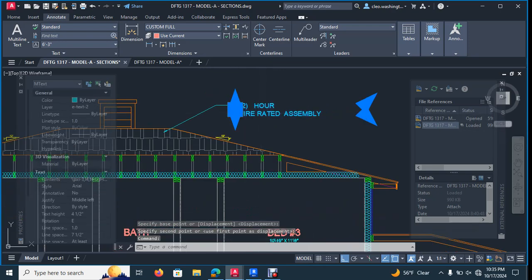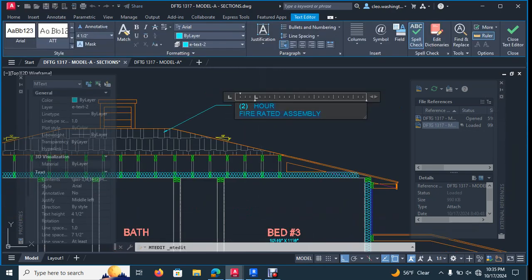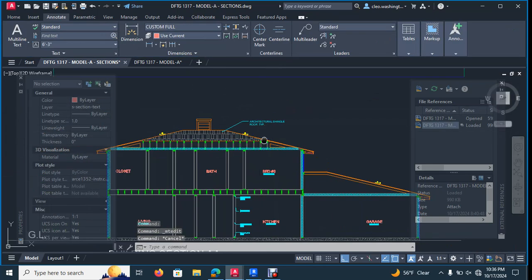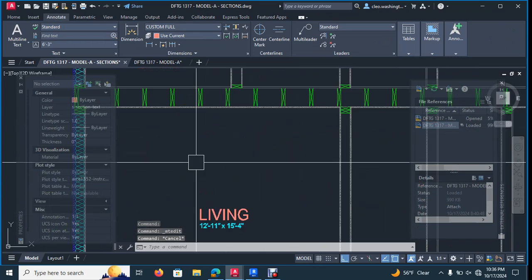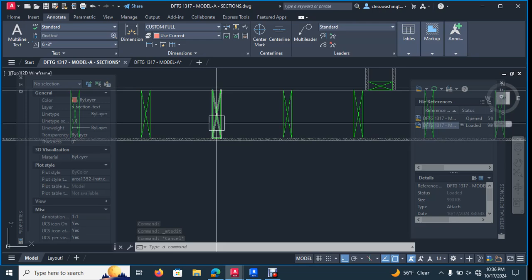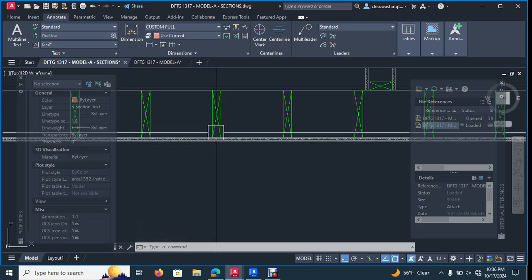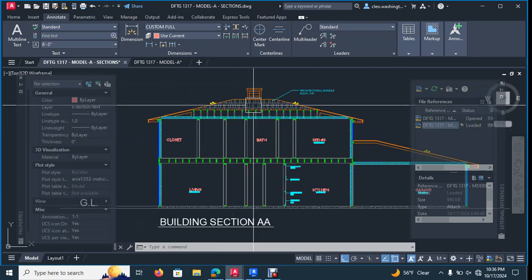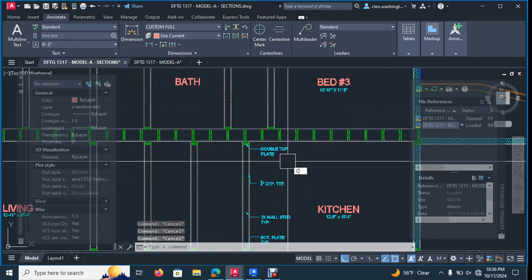So here you would come and you would say, enter roof, comma, TYP, period. That's all you would do. And you would call this out as 2x12 floor joists. Okay, let's go ahead and copy this over.